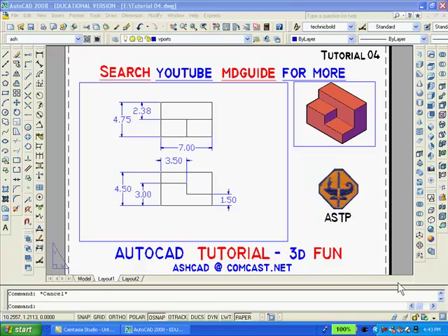What you are looking at now is my 2D drawing and solid model of the object. If you look at the icon in the lower left corner of the screen, you can tell that the drawings being displayed are in paper space because a small right triangle is shown. The first thing to do is to erase the large and small viewports.